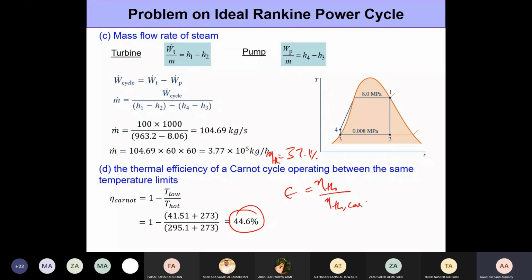And since this is a heat engine where it converts heat to work, you could use the formula that we discussed sometime in the last week. So it's the thermal efficiency of the cycle divided by the thermal efficiency for the Carnot case, or for the maximum thermal efficiency. And for this case, it comes out to be 83%. So you can see from exergetic efficiency, it's already pretty high. It's not so bad. It's simply bad because we're looking at energy-based efficiency, and this is not giving us an accurate picture of what's happening. All right, questions? Any questions here before we move forward?